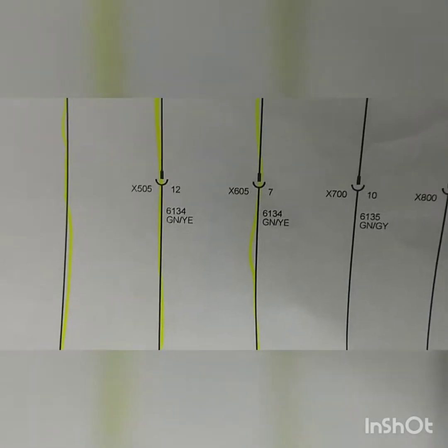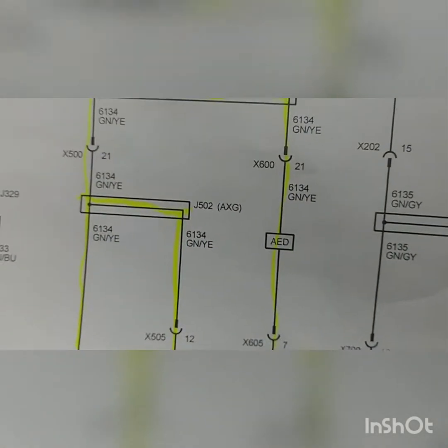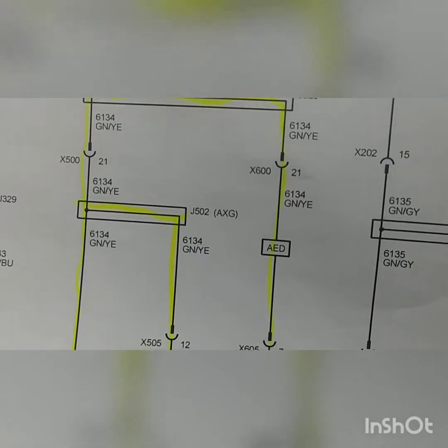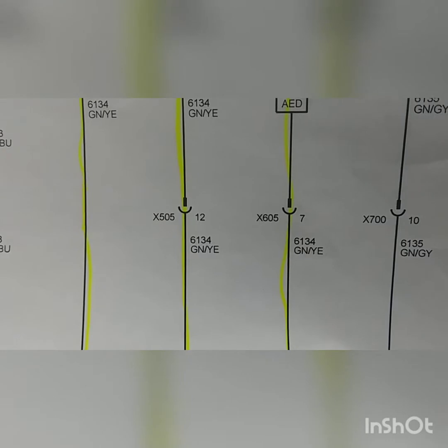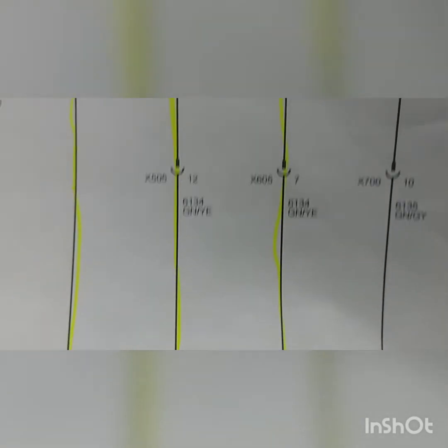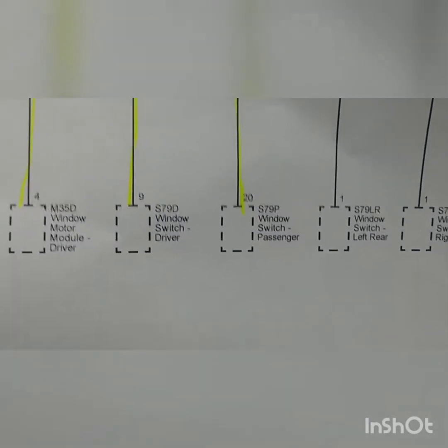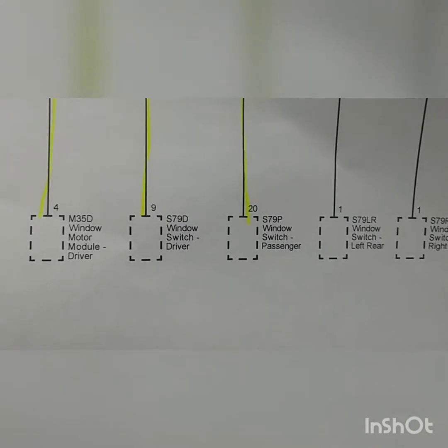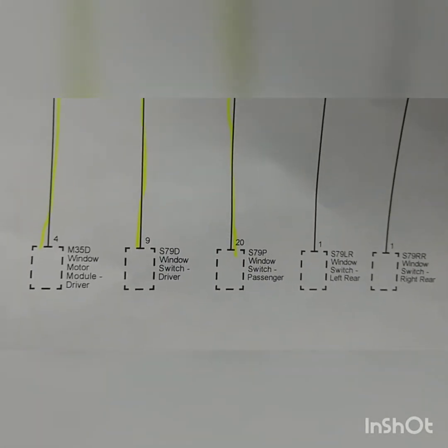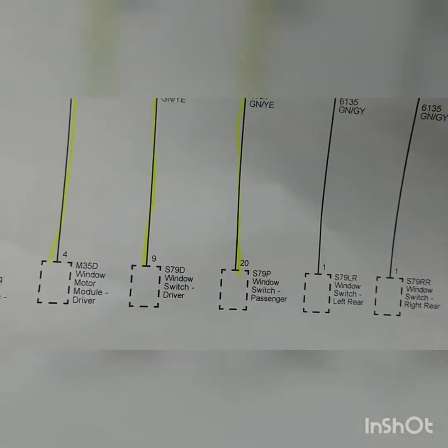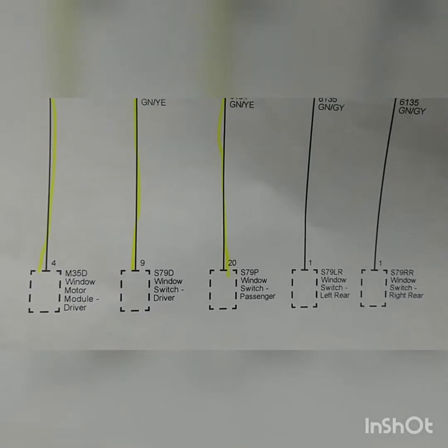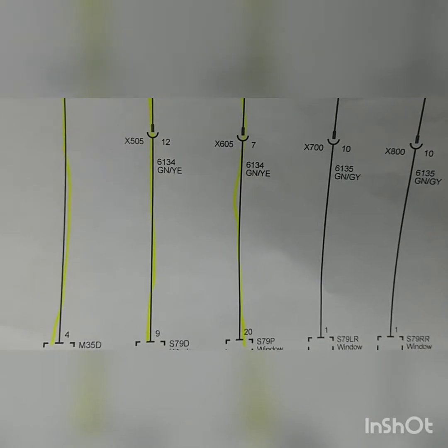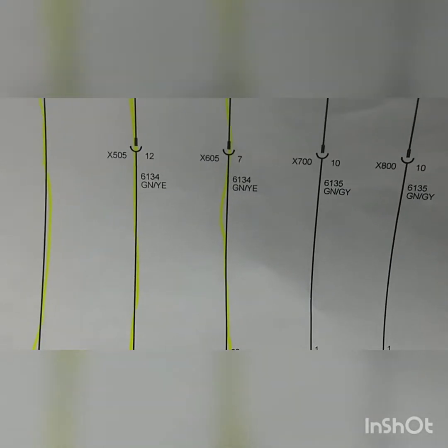But as you can see, we followed the electrical path, and we disconnected 605. So we didn't make a mistake about that. Maybe that was a quicker way, just to pull up the panel and back probe that window switch and disconnect it, and see what we've gotten. But we did disconnect the 605. We did the right diagnostic procedure.